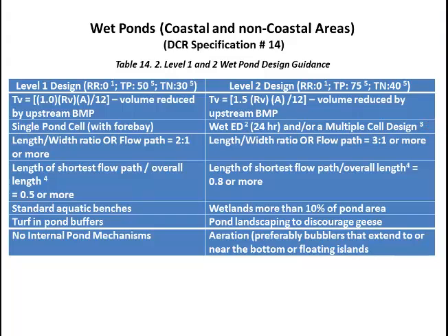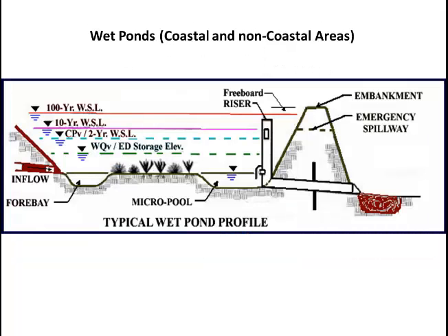The total volume of all 4 bays should be at least 15% of the total treatment volume. The total water quality volume storage may be provided by a combination of the permanent pool, a shallow marsh, and/or extended detention storage. The maximum extended detention volume associated with the treatment volume may not extend more than 12 inches above the wetland cell permanent pool at its maximum water surface elevation.